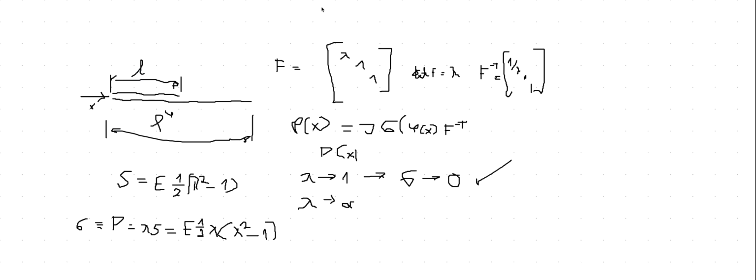Basically, with this constitutive equation, lambda will go to infinity linearly, lambda squared will go to infinity quadratically. I can say that the sigma will also go to infinity. In other words, the physical observation, which is entirely correct, is that if I really have to introduce a very large strain in a reasonable material, I have to put very large stress. Otherwise, you don't do that so simply.